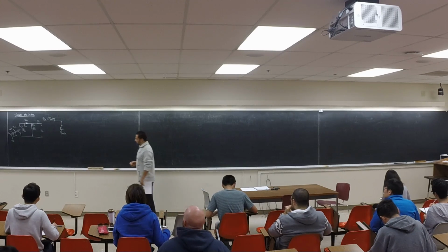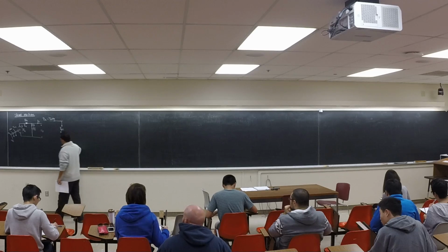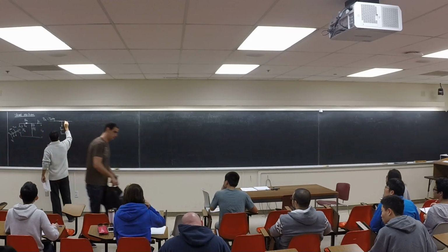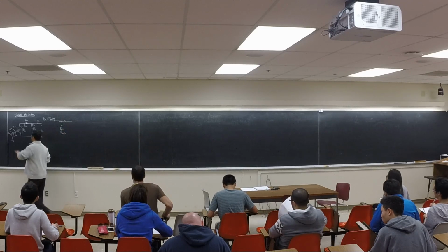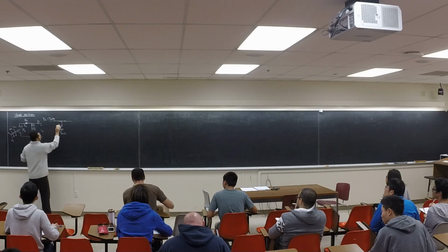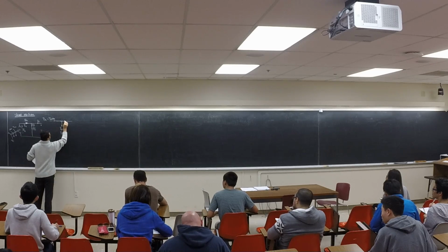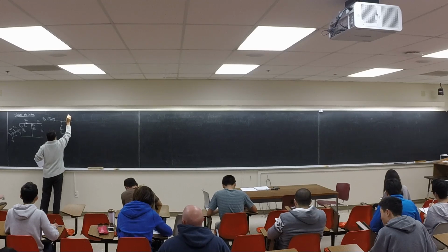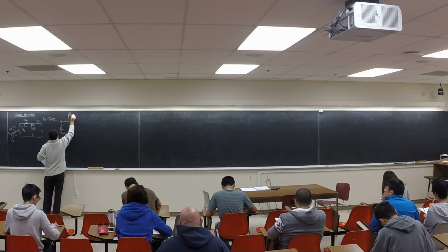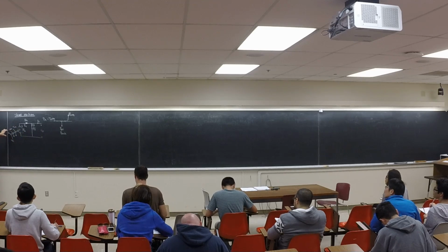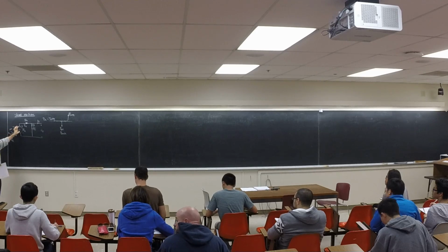Mechanical loss is this one. Now, this one comes to the machine, right? This one is going to be equal to EA, IA. Actually, if you look at it, there is going to be core loss. You're going to have some losses, hysteresis loss, eddy current loss, those kind of things inside the rotor.